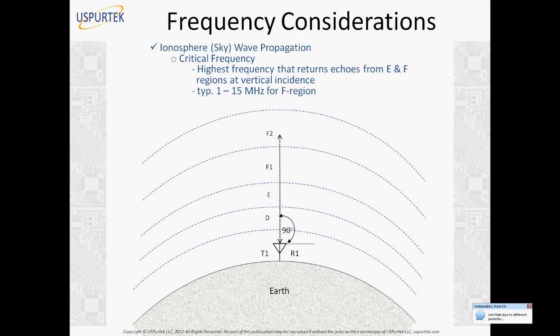Well, there are a few more things that any operator using skywave propagation has to worry about. So one is, there is a question here: isn't that due to different permittivity of layers? Yes. In this case, yeah, permittivity does have a role to play here. About ducting you are talking about, yes. Permittivity does have a role to play here. Because of permittivity, it will stay over there and return at an appropriate point to the Earth.